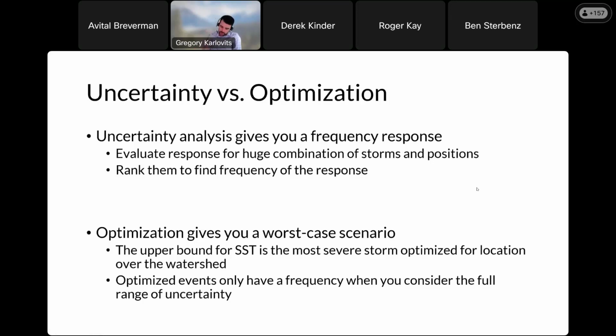that is the most rainfall that we could potentially get in this catalog. And I'm going to say that in most applications, both in literature and what we've tried, we're generally looking at an event, when you do the full uncertainty analysis, that's generally something rarer than 1 in 1,000, 1 in 5,000. It really depends on the luck of the draw in the catalog. So it is a pretty rare event when you start optimizing some of those.